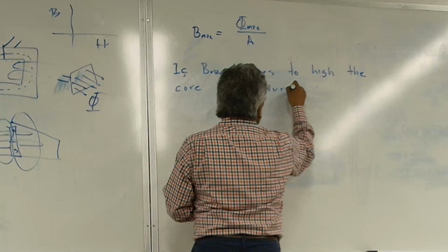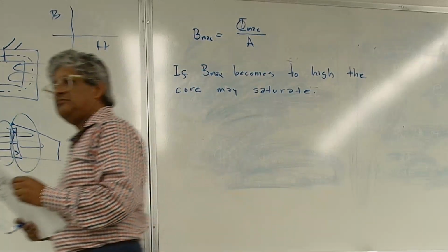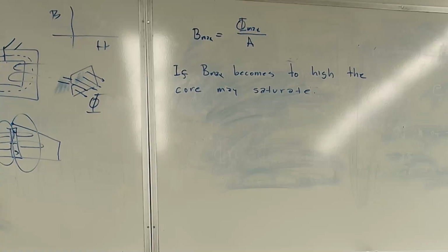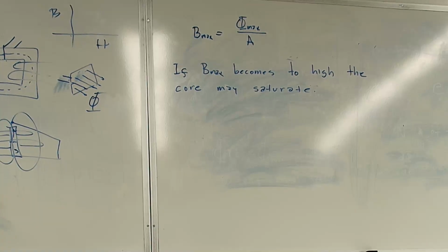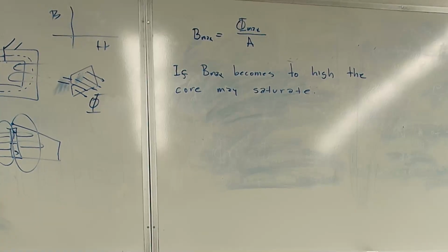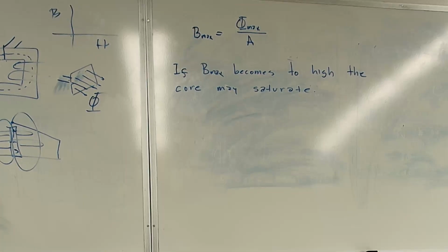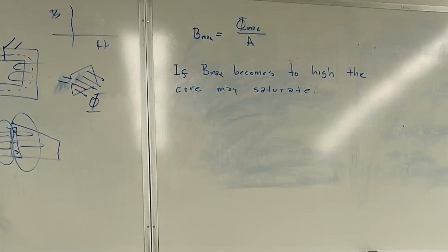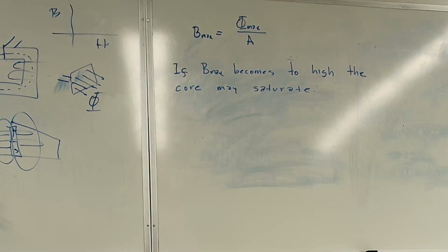So you have effectively lower efficiency. You reach a threshold where you can't conduct. You want to make sure that the transformer is operating in the linear region of the hysteresis, right? That's really what it's boiling down to. If the flux density is too high, you saturate. No matter how much current you're putting in, you're not developing voltage out of that transformer. So you're losing.